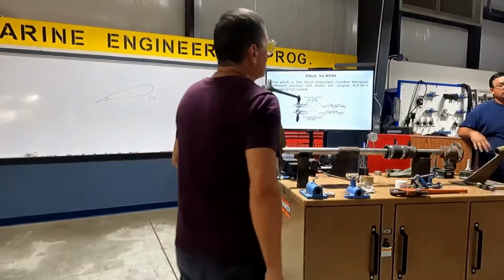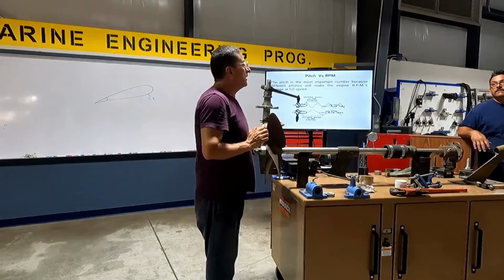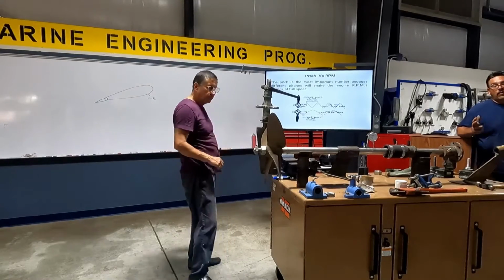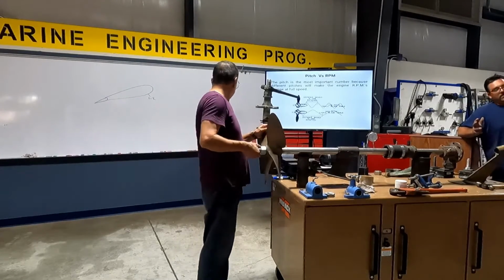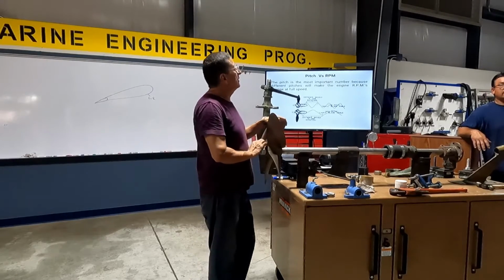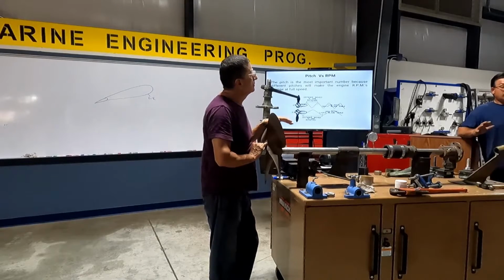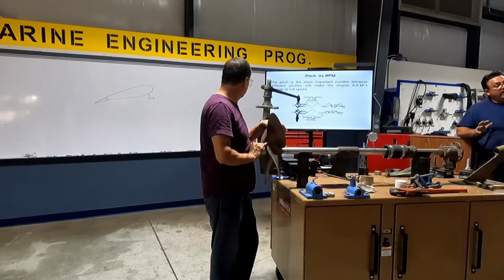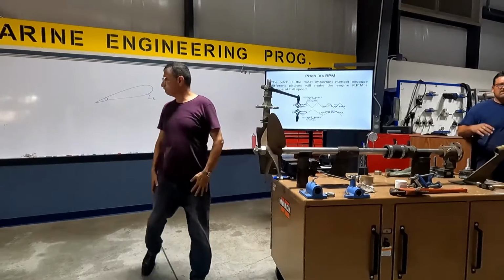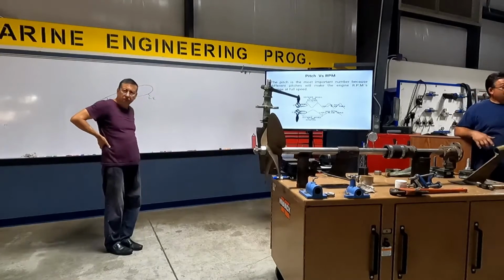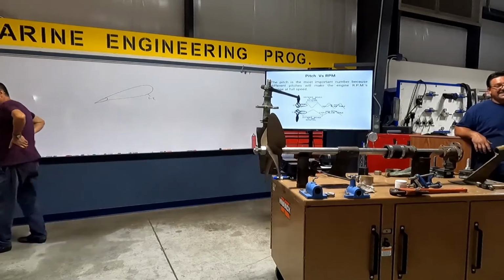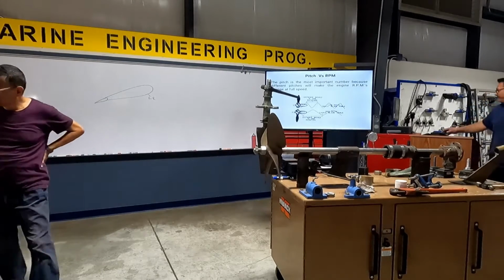You have that guy. Danny, I have a question about the cup. It's very common in outboard propellers, no? Yeah, in the more quality prop you have, the more cup you have. Cup just gives it a little bit more bite, less slippage. There's always a slippage, just not as bad as aluminum, but you still have slippage. Your cup just kind of gives it more of a bite. Do the cups wear faster than the water? No. The only reason props wear out is because you have a guy running through the sand. That's the guy who's gonna wear the prop.